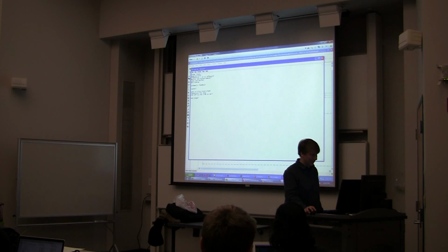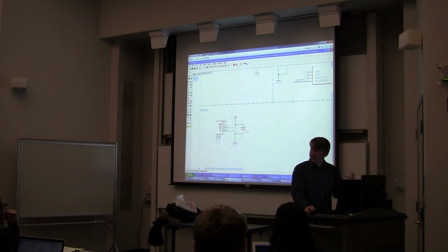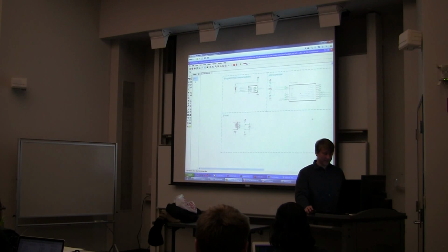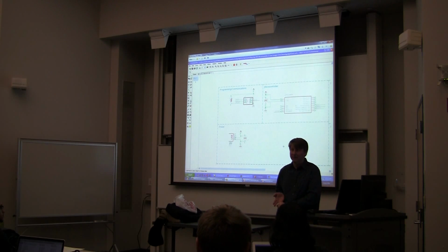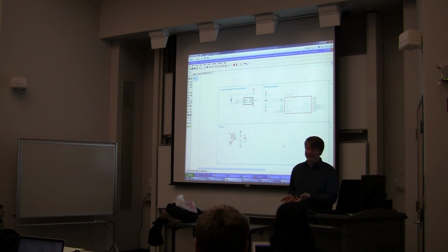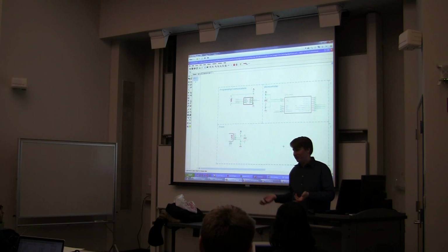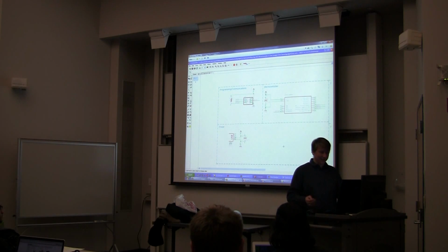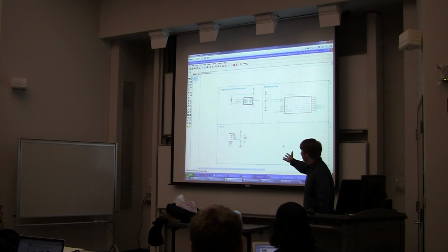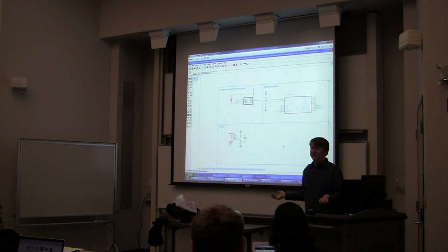I got my power. Do I want regulation? I'm going to say no. Maybe we'll come back and look at how you put a regulator in there. Usually they're a good idea, but you'll notice your mini gadget does not have a regulator. That's because we say, well, the battery can only provide somewhere between 3 volts and 4.5 volts. There's no way we're going to get 11 volts out of this thing. It's probably okay. And same here, I'm saying I'm going to plug directly into the USB port. I'm probably going to be okay.